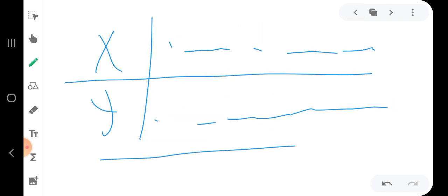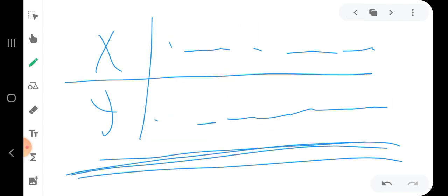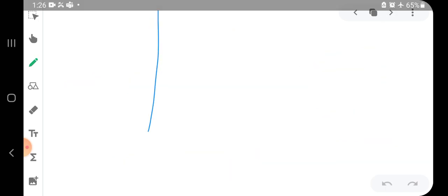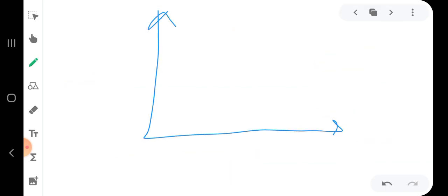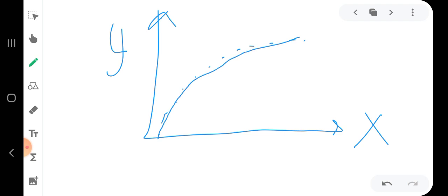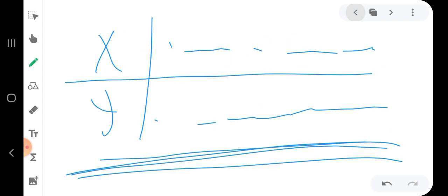We are going to apply the same thing. If we are given the equilibrium data, we are going to plot them. We will draw our axes, x, which is the mole fraction in the liquid phase, and y, the mole fraction in the vapor phase. We are going to plot the points given, and then connect them. This is called the equilibrium relation. Now, what about the material balance relation?